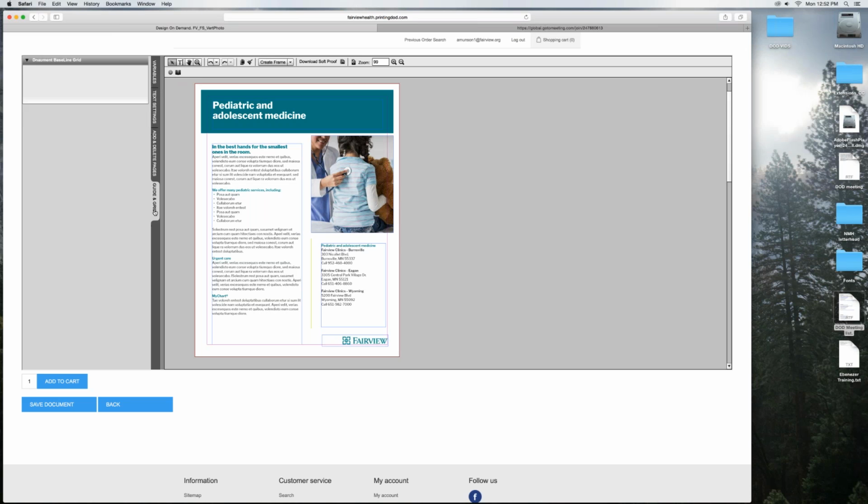Number one, in these tabs here, you do have a set of guides. As you can see here, they're spaced out starting at a default of 0.5 inches from the top. You can see we just moved it down to an inch, and we're going to put a 0.5 increment in between. You can shut them off either by undoing this checkbox, or the toggle view button will shut them off. So we will go ahead and shut those off. If you do need a vertical line, you will have to use a line out of the Create Frames pull down.